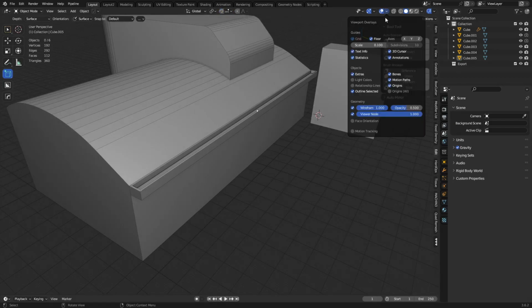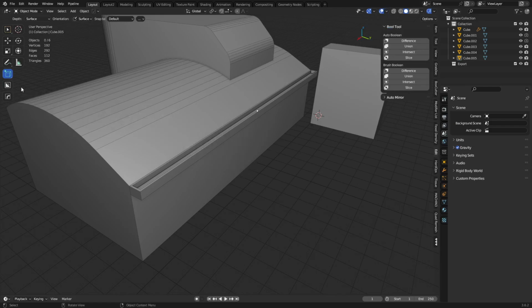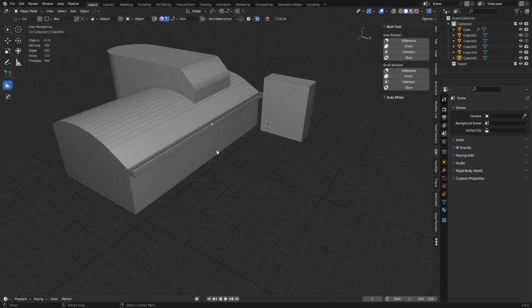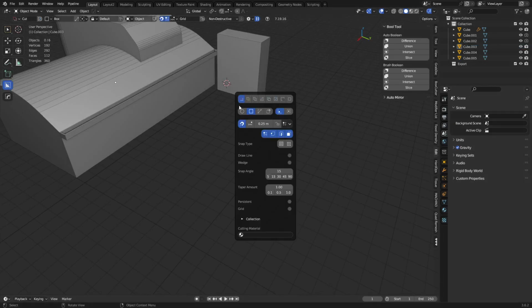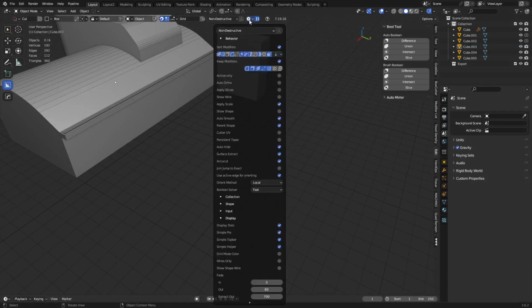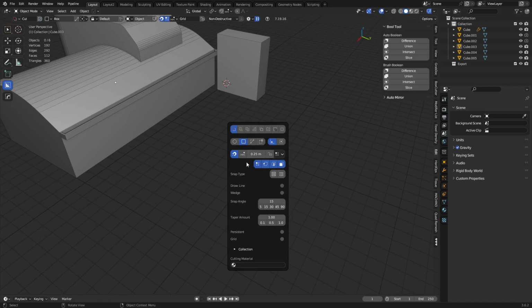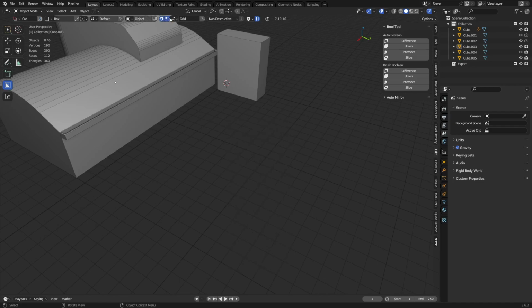I'm going to turn snapping off for a second, set this back to 1. Let's go over to Box Cutter instead. All right, so Box Cutter by default, when you press the D key, you have a different menu. So let's go over that. Under display here on this drop down, you can set simple pie. I find this one to be extremely useful in combo with what's going on up here.